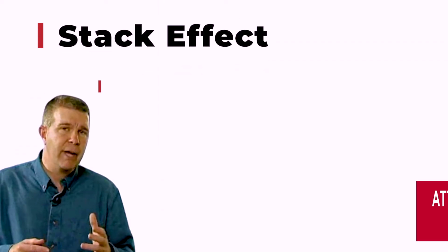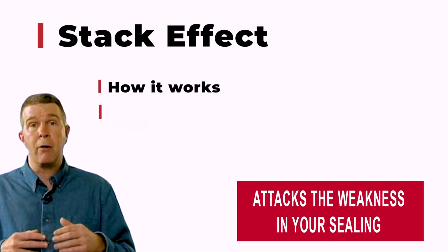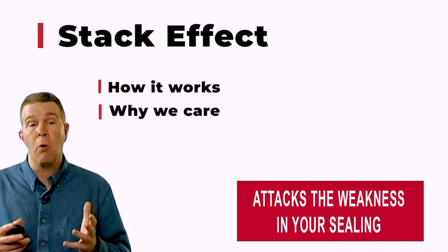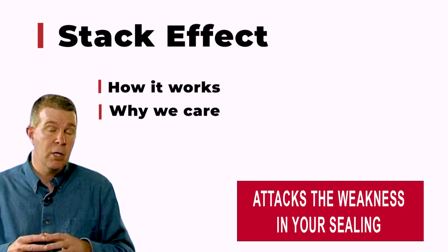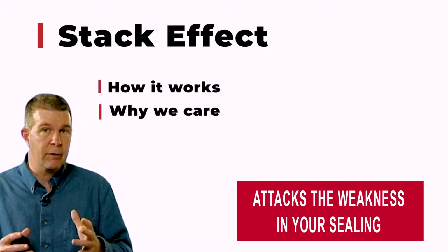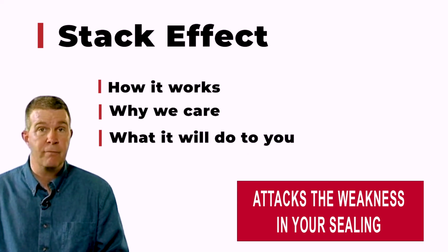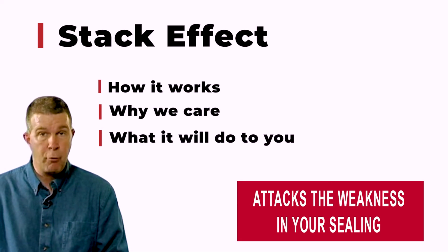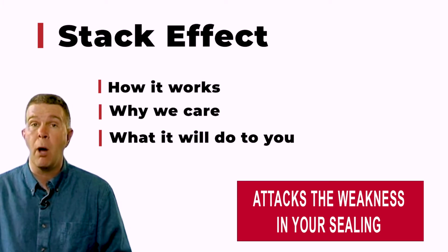In the stack effect, I've described how it works, and there's a big reason we care. The reason we care is because it's going to move air where we don't want, but most importantly, it has to do with the crawl space or the basement. When you have that negative pressure down there in the lowest floor of your structure, it's going to pull that stuff in through the walls or up through the floor.